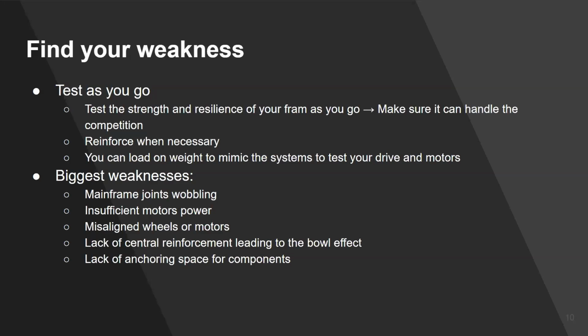So make sure that you have enough width of your materials that you're using, or enough joints that when you have to put your components on, you've got somewhere to anchor it. That's not just adding on, like, oh, okay, let's just add a little bar here or a little bar there and see if it'll kind of work. No, think about those things beforehand. Make sure that your frame is ready to handle the components that are being put onto it in a way that is conducive to them working.